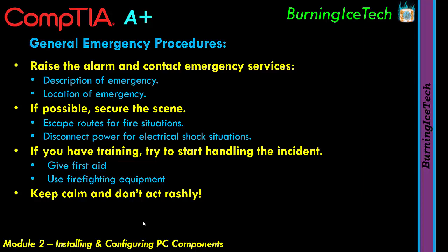Disconnect power for electrical shock situations. So in the event of the emergency being electrical related, if possible, turn off the power. There are exceptions. For example, if there's a fire emergency, you also preferably want to turn off electricity, because you never know, it could actually make situations worse. So depending on the situation, there's a very good chance you might need to trip a circuit breaker somewhere. That's what you want to do.